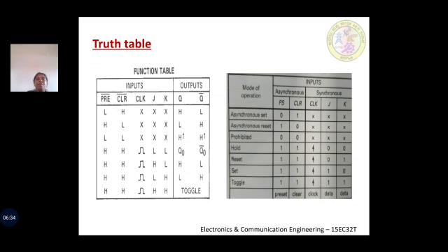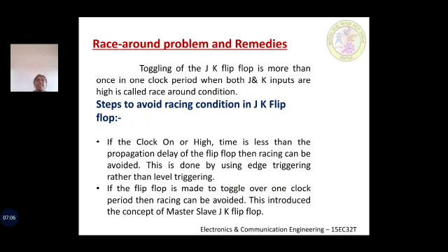to the flip-flops. The first case, when Q and Q bar are H and L, is known as asynchronous set. L and H is asynchronous reset. High Q and Q bar is known as prohibition state. Q naught and Q naught bar is hold state or previous state. Q and Q bar H and L is synchronous set state. Q and Q bar L and H is synchronous reset state. And the last case is toggle state. So this is a brief description about the asynchronous inputs to the flip-flops.